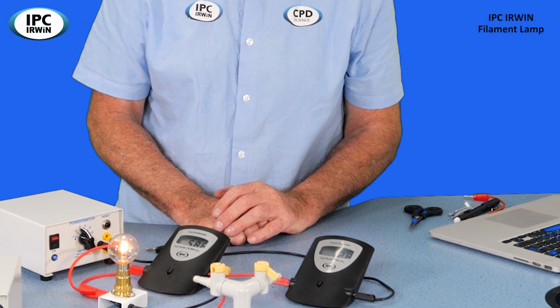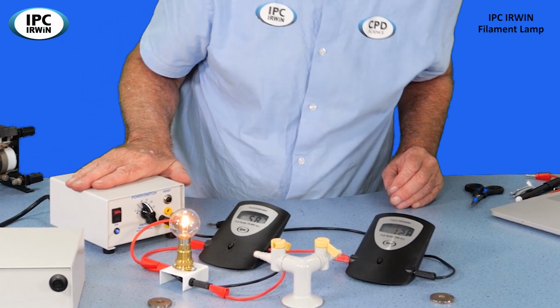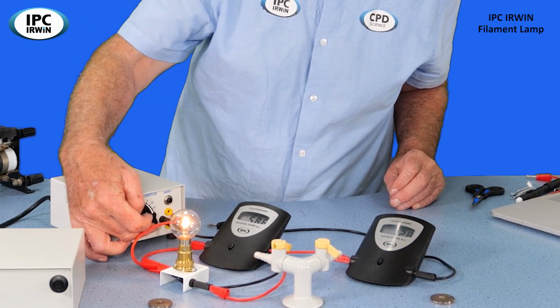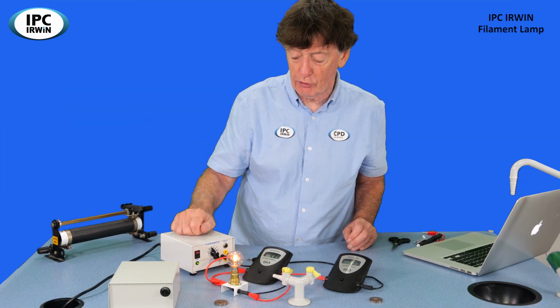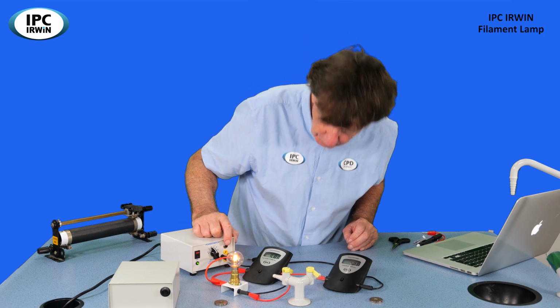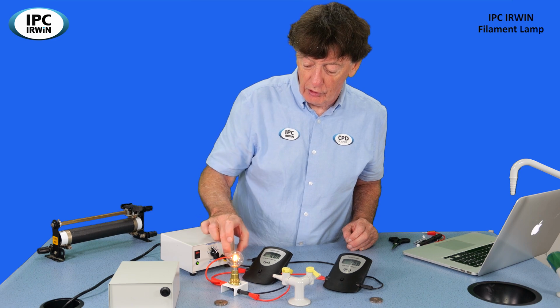So we'll use this circuit initially. We've got an IPC Irwin low voltage power supply there. It's got a rotary selector switch there from 2 to 12 volts. So they're just approximate potential differences. There's a cutout. It'll provide at the most 5 amps. And it's also got an AC supply. So we're using the DC supply.